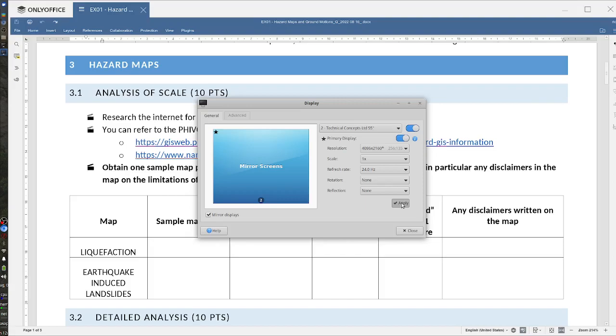And that would have a significant bearing on the liquefaction hazard. Okay? So if you're standing on gravels, there's no potential liquefaction, or cobbles or clays, okay? As opposed to standing your structure on silt or sand. Okay? And that condition can easily vary within a few meters.